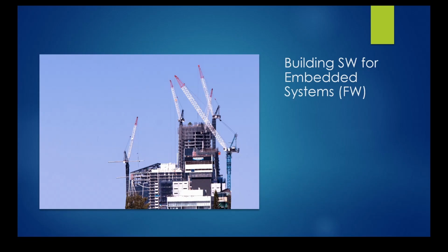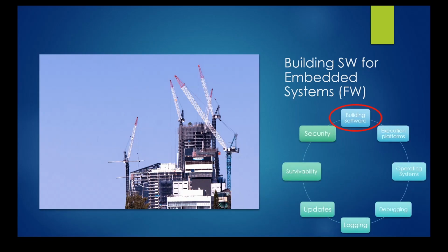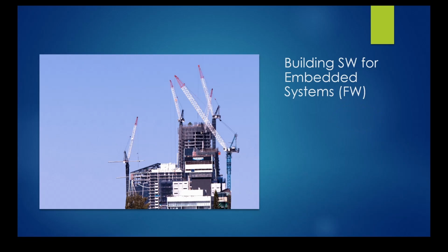When building firmware or embedded software for embedded systems, we find additional things we have to consider. When we build regular software on a desktop PC, we usually get directly a product in the form of an ELF file or other similar formats that includes all the build products: the runtime binary, linked and ready, the debug info if we chose to include it, and other metadata like code relocation data, section data, and so on. The operating system takes care of loading such binaries, and it's usually seamless to us.